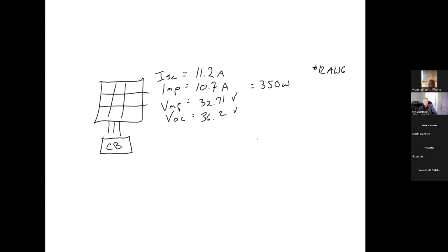That's just what we get in today's solar panels, residential for sure. So what is the limitation of a 12 gauge wire? And I think it's somewhere in here in the early 100s. Here we go. Yeah, page 104. So 12 gauge wire, we read it from the left-hand column. So 12 gauge wire has 25 amp capacity. So 25 amps, well, let's make sure that we're within that.